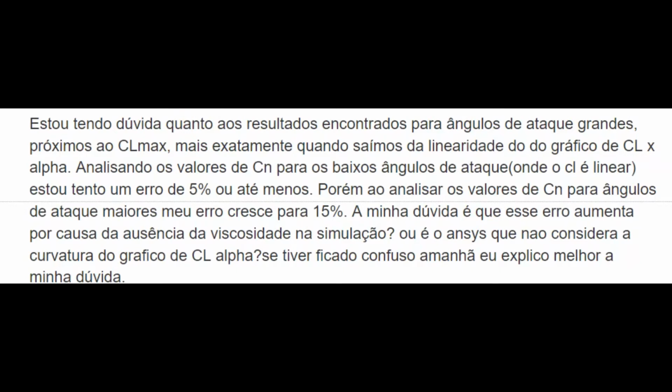When you start to have a stall condition, the main reason of the flow separation is the boundary layer and viscous interactions with the flow. And since you do not have correctly calculated viscosity and correctly calculated boundary layer, of course, this error grows. The error grows. And it's normal. I already explained to you, don't worry. In work 2, you can have this error growing.